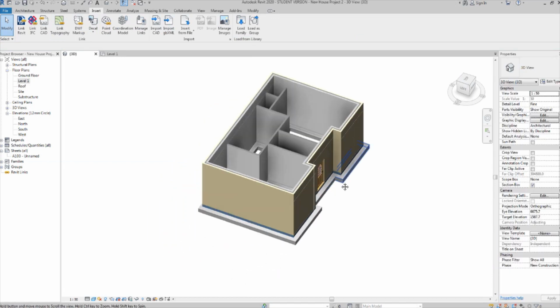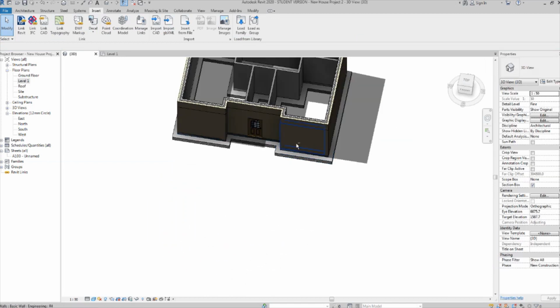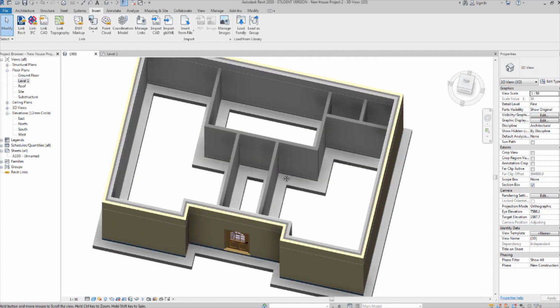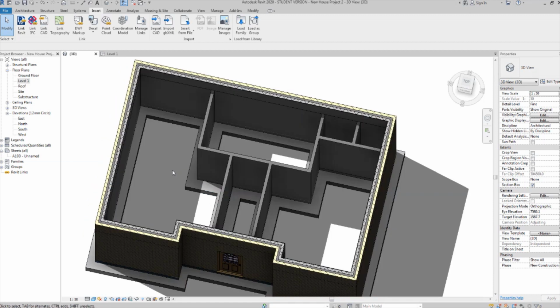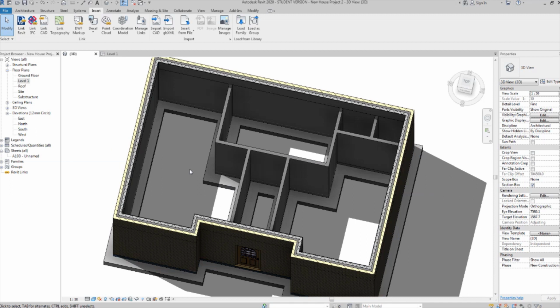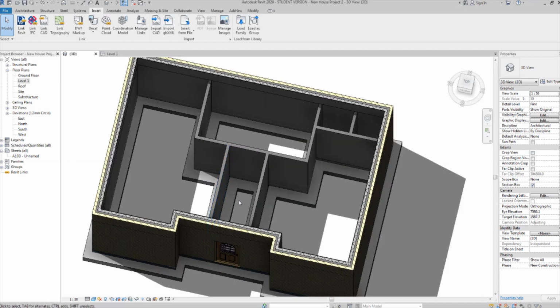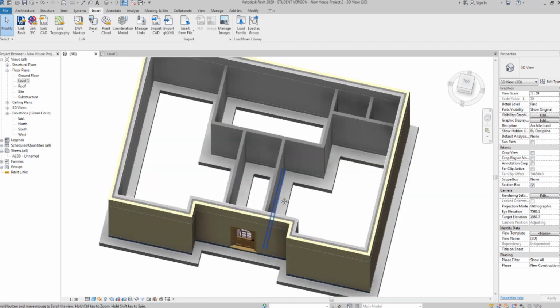Okay, now what we want to do here, in part 2, is add floor joists in each of the rooms and then add a ground on top of it so that the ground is elevated from the soil and it won't sink through these holes, so that we can actually walk on it.